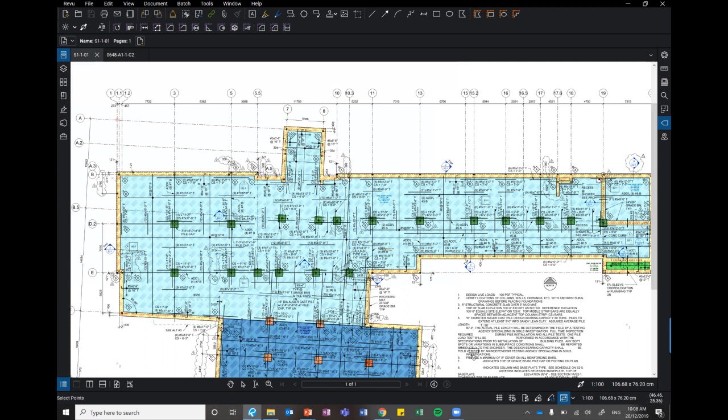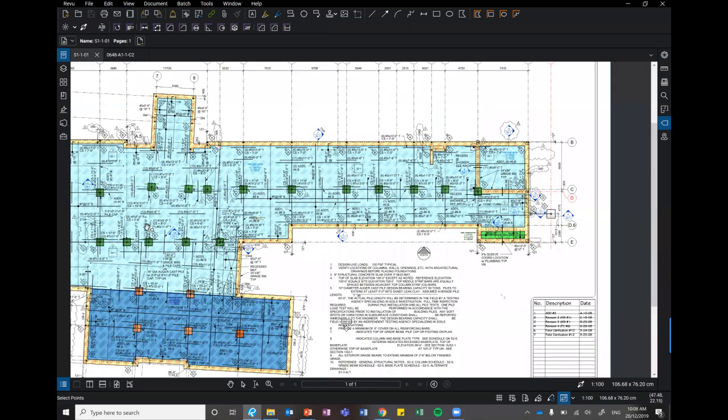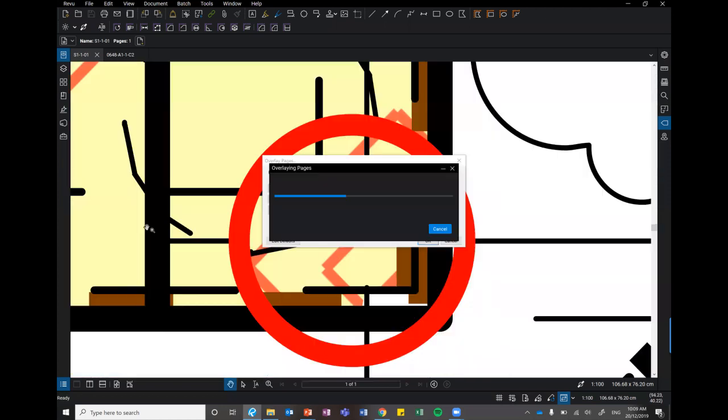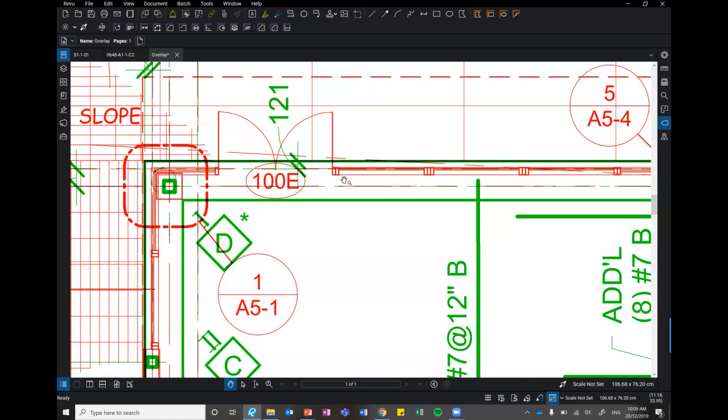So you might be a builder that's done a whole costing of all the different areas. So you do your pricing, and then I'm just going to do a final check that my slab layout and all my quantities are going to work, because they definitely coordinate with the architect, because unfortunately my volumes are from the structural engineer, but my set outs are from the architect. So I need to make sure we've got an alignment here. So you can actually see we've got different size drawings as well, but we can follow this in, and it's hard because we've got different consultants, but we can see the slab edge. That's what I'm focusing on. We have the same information.